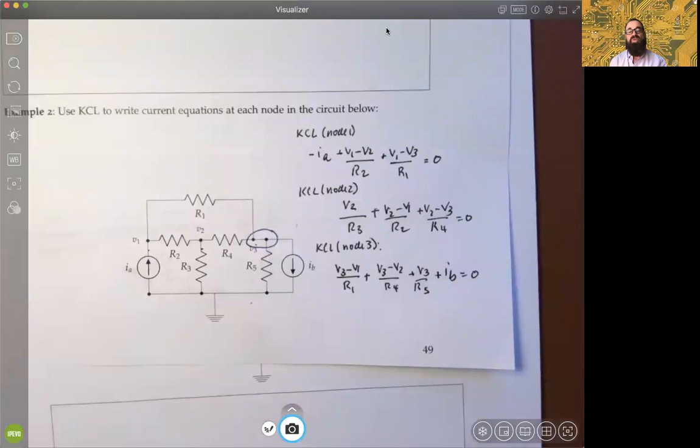So again, 3 equations, 3 unknowns. The unknowns are all the node voltages. We're going to stop there, and in the next lecture, we'll set up the linear system that looks more like how you would solve a problem in, say, your linear algebra class. But we now know how to use node voltages to find the particular voltages at any circuit element using their differentials, in other words, the difference between the node voltages. And that way, we're getting representations for the currents as well.